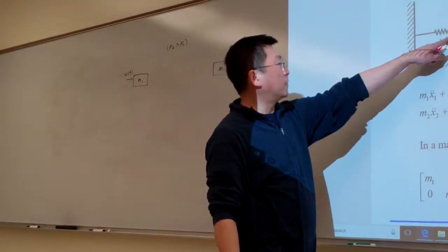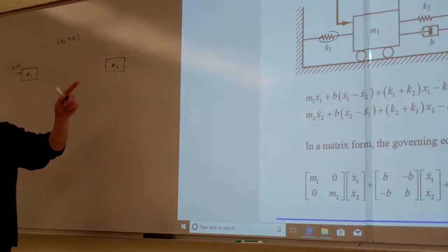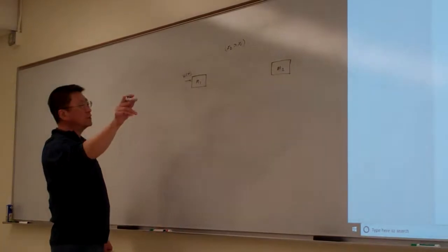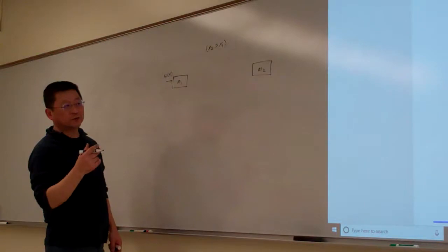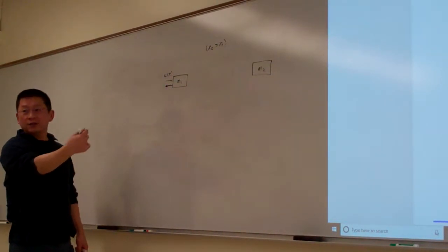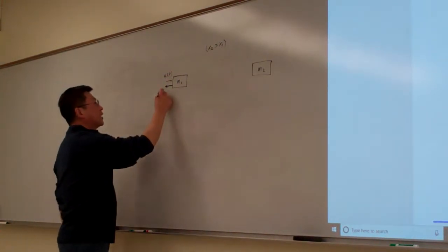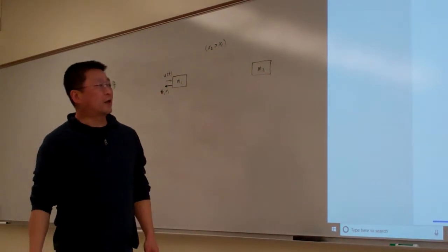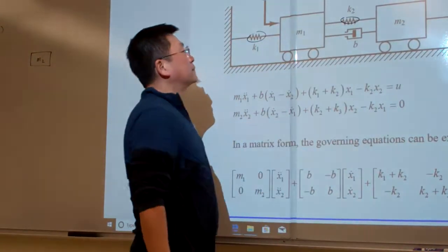Okay, now from here, let me work on this one. Due to the displacement, the degree of freedom assigned is moving rightwards. So from here, spring K1, based upon the configuration we assumed, will be stretched. That means it's going to provide a recovering force in the opposite direction, and that one is equal to K1 times x1.